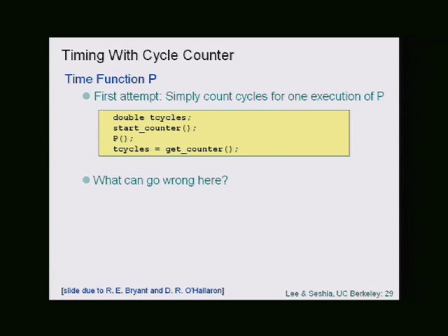How about for embedded platforms? There's often power management, right? So you have dynamic frequency and voltage scaling. So think about frequency scaling. If that's happening while your task is running, then one cycle doesn't mean the same thing. So you might get a certain cycle count, but you can't translate it into a second or millisecond value in a straightforward way. You need to know what the frequency was when you were running it.